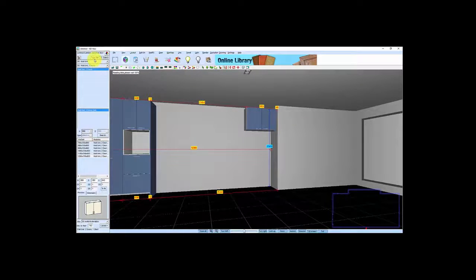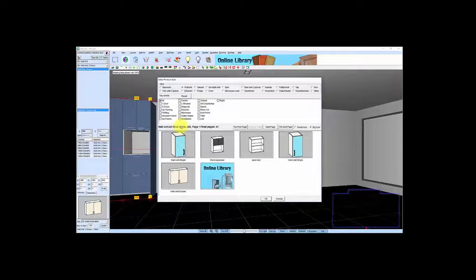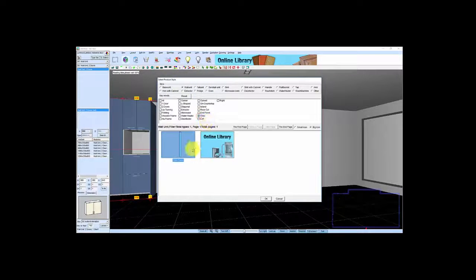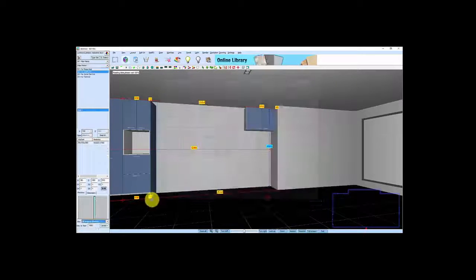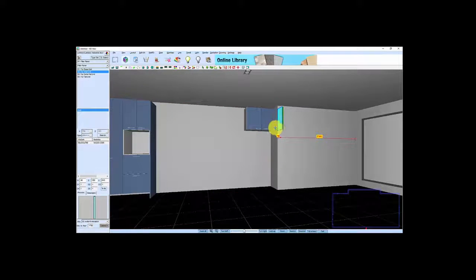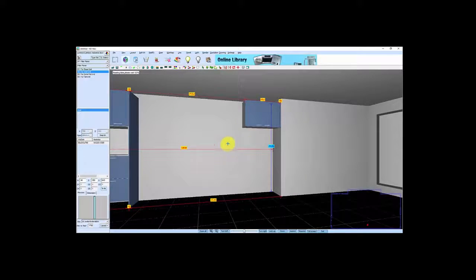What I'll do from there is I'll go Type Select, wall unit, I want an end filler panel, go to filler, go OK, change that to 40, keep it at 350, 640 high, and I want it at 1760 off the floor. Press layout, drag it there and butts it into and just go no. So there's my filler for there.